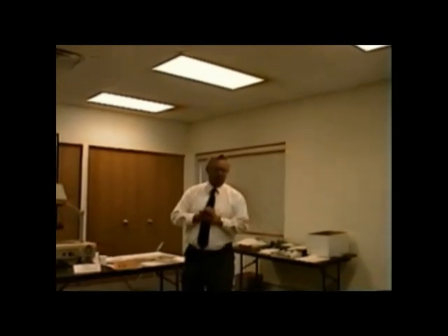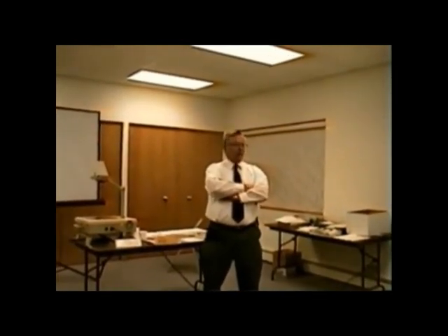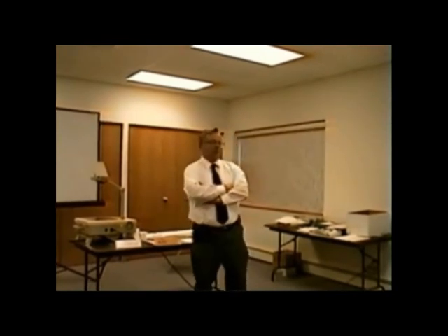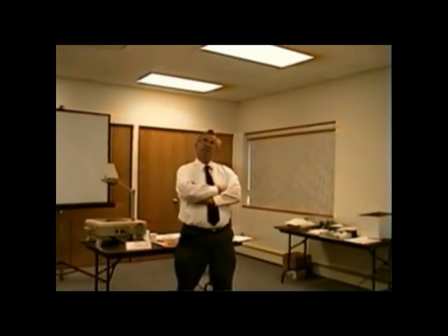Okay? Let's talk about that a little bit. When we check vent temperature, gentlemen, we're telling you to poke a hole in the vent, right by the furnace. Now, if it's an 80-plus furnace, now you've got a hole in the vent. What do you do? Leave it alone.